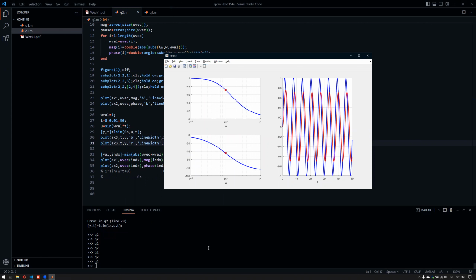So you can see there's a little attenuation, which is expected due to the Bode plot here, because the lower the frequency, the better this transfer function just passes and doesn't attenuate. And the higher the frequency, at this point, actually, we're almost at the corner frequency. If this would have been a filter, we would then say that this part is basically rejected, this part passes through this filter. So that's kind of the business that we get from this system here. The system behaves like a low-pass filter.